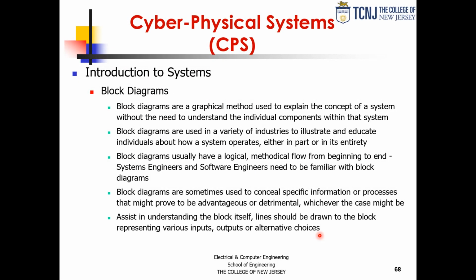then you'll find out something that I didn't put here, that for a step function, you would get like Kp, but that Kp, Kv, Ka, which stands for position, velocity, and acceleration, is really tied to the old days when they were trying to do analog control of mechanical systems, so I decided not to put that in there.